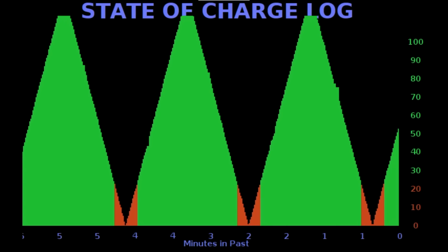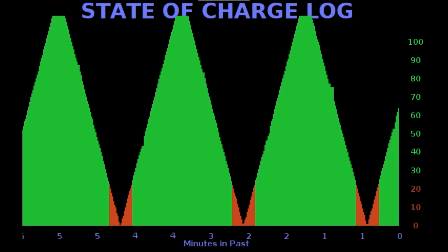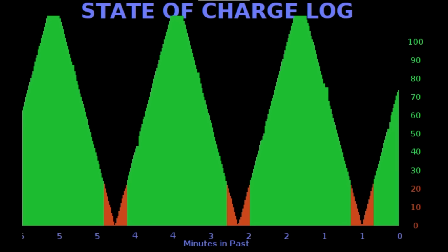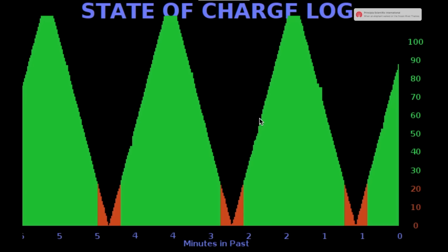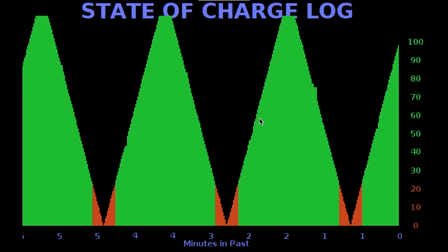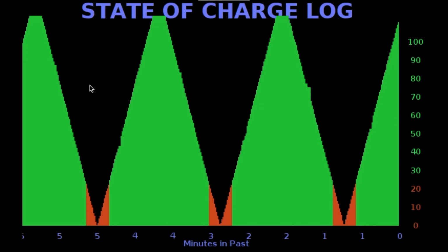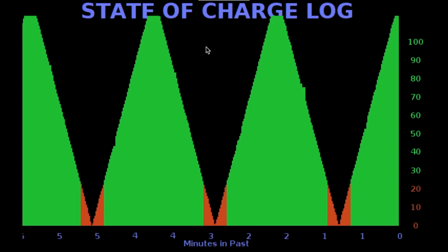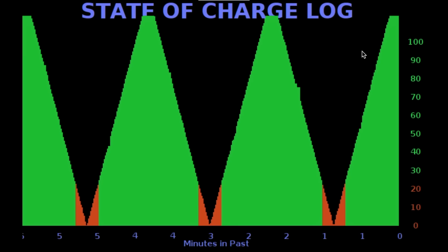Now our thinking on this is evolving, but we're probably going to do this logging at a much slower rate. If we did it every 120 seconds, for example, sampled the state of charge, which doesn't change nearly as fast as our power output, we could have the last 24 hours on this display, showing us our discharge, the state of charge going down at night and coming back up during the day, and we get a big curve here, and that's what we're working to.